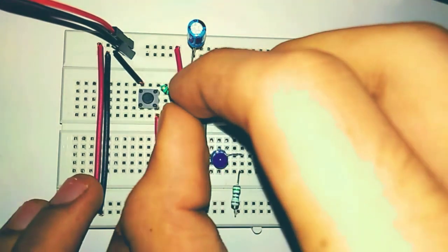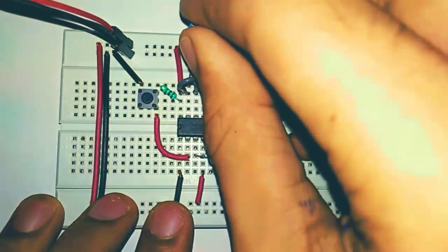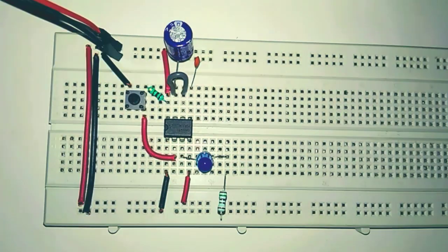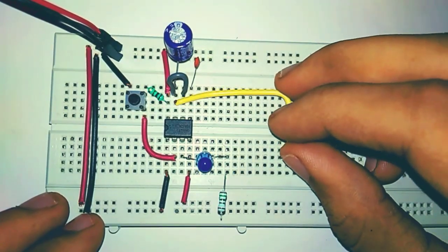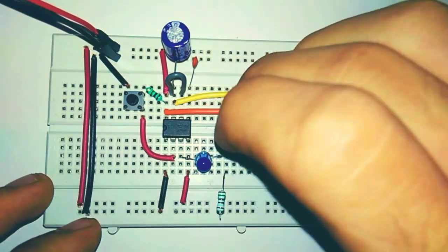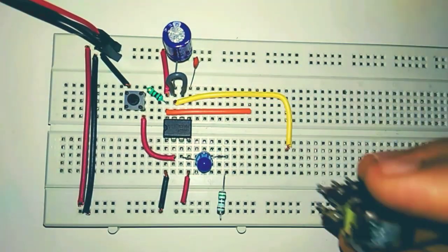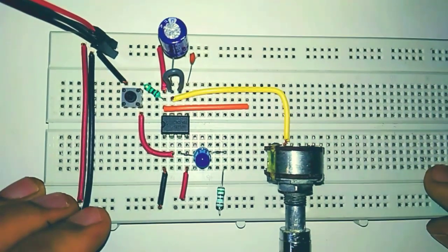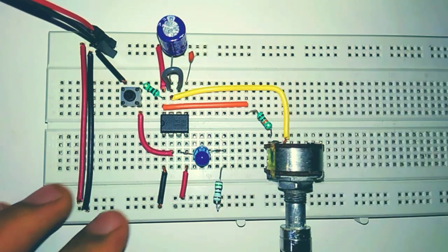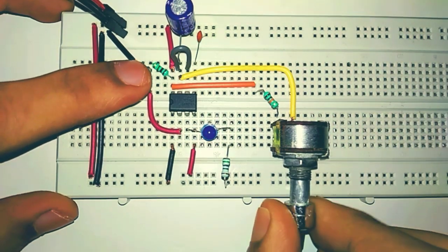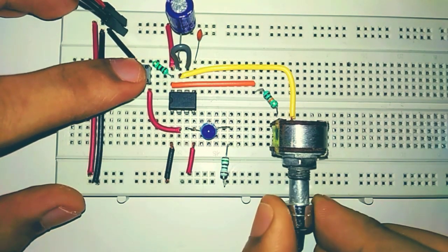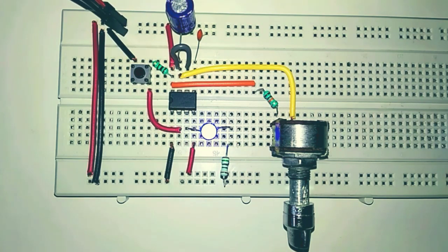We can replace the resistor R1 with a 100 kilo ohm potentiometer to change the time width easily. Before that I'm going to replace capacitor C1 with a 100 microfarad capacitor, to get a larger range of adjustable time width. I am also adding a 10 kilo ohm resistor in series with potentiometer to act as minimum resistance when potentiometer is at 0 ohms. As you can see, we can now adjust time width without changing any component. In this circuit you can adjust time from around 1 to 12 seconds.